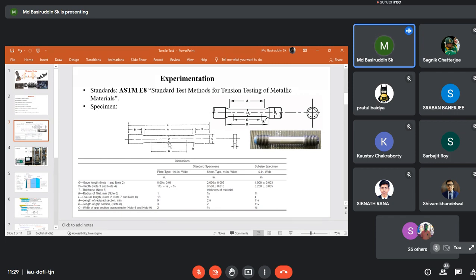And otherwise, I think for civil engineering cases, we will find that whenever you do the tensile test of a rod, meaning TMT rebar, in that particular case, they try to gauge or mark throughout the length of this particular rod. Okay, and then before doing the test, they take the measurement of the length of the rod, and after the test, they take the measurement of the whole rod. Okay, not the nearby regions of the fracture surface.